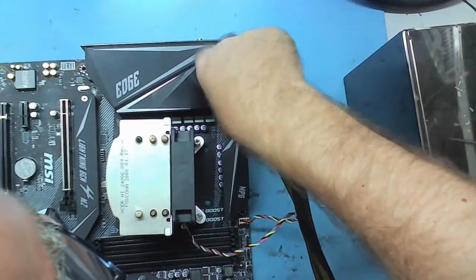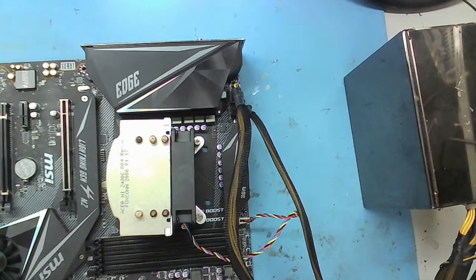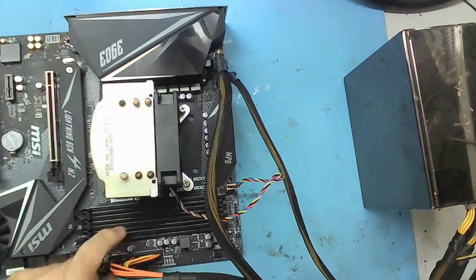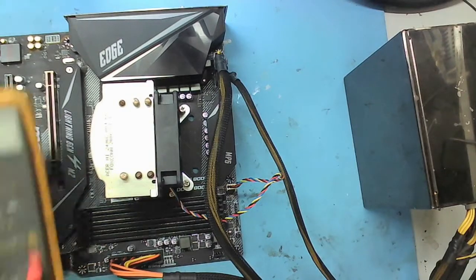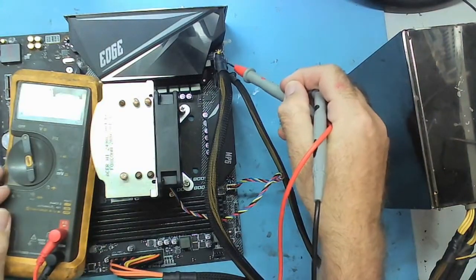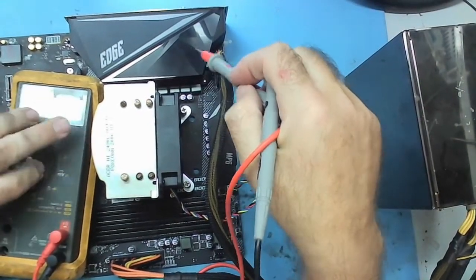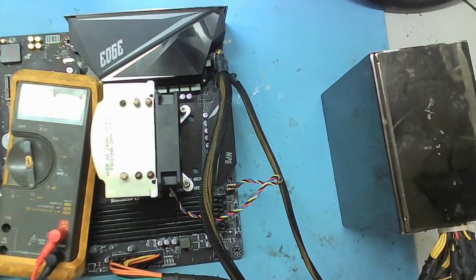8-way down there. Yeah, one more thing I think it's worth testing on this before we power it up is, do we have a short on here? I'm not so bothered about ones down here particularly. Probably is worth checking though. But do we have a short on this? Because this powers the VRMs, and if you've got short circuit MOSFETs down here, if you use a decent power supply, a good brand, it'll just shut down. A cheap one, it might blow the power supply. It certainly won't do the board any favours. It certainly won't do your processor any favours.